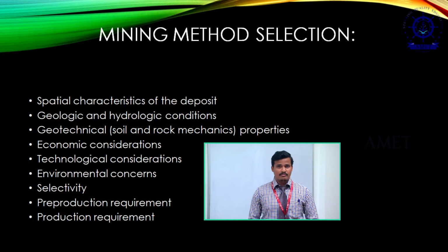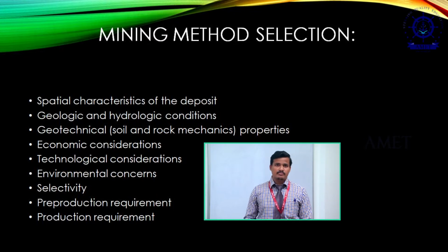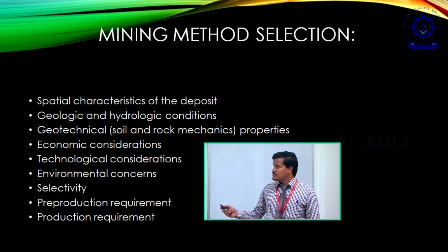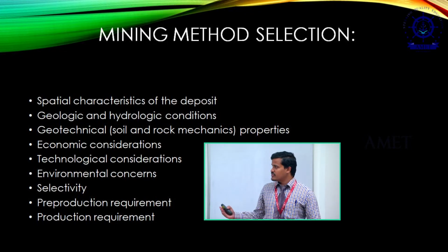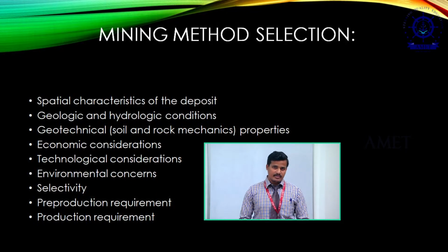Whereas if the deposit is more than 1 kilometer deep, for example in South Africa, there are many mines which are about 4 kilometers deep and still they are mining economically. Such mineral deposits have really high value, and most of the deepest mines are for diamond or gold. So, based on the spatial characteristics, they will choose what sort of mining method they are going to use. The second one is geological and hydrological conditions. So, what is the water content in the particular area?